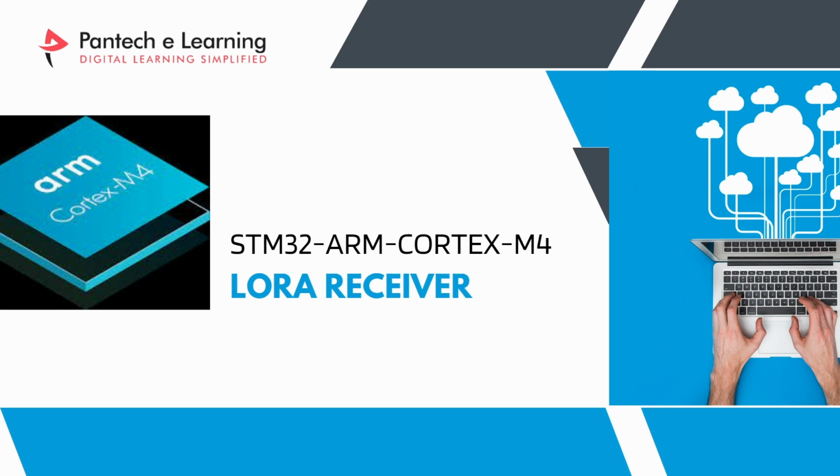And what is the role of this ESP32? As I said, we will not get network or cellular data in the farm. So I need to transfer data somewhere, right? The user has to see the data or operate it by mobile phone, smartphone or a PC. So we are going to connect the LoRa receiver with this ESP32, and we are going to connect the LoRa sender with this STM32.